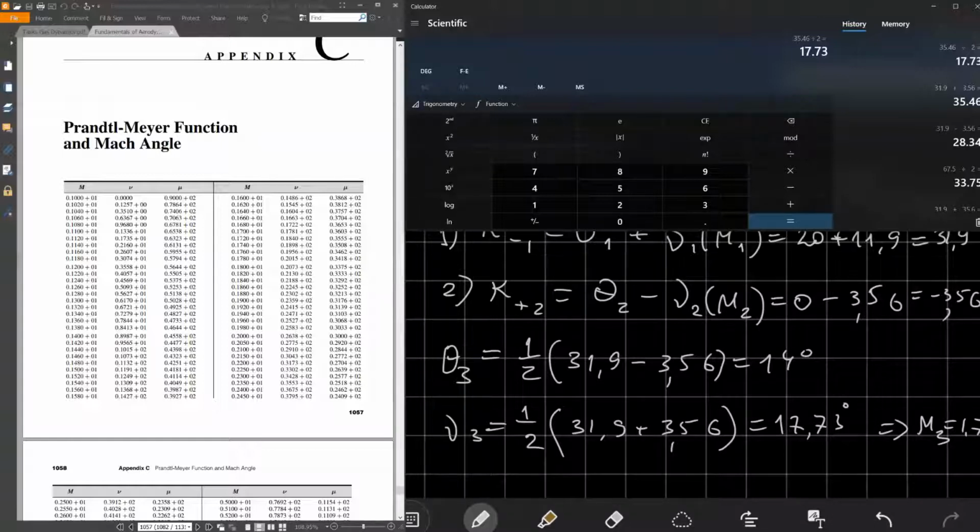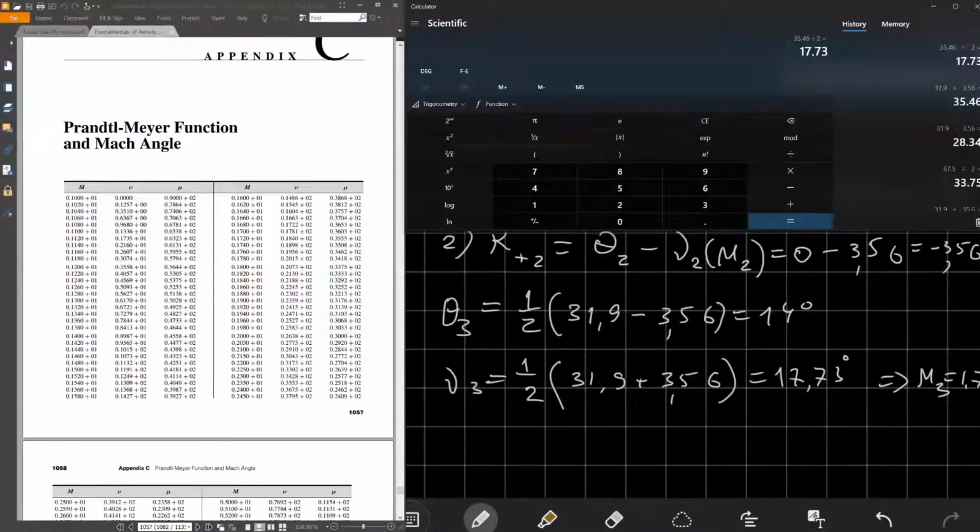Flow acceleration is happening in the middle between axis and the wall. So this is the end of calculation for the wall. If you would like to calculate thermodynamic properties, it's shown in the book how to make it. It's just apply isentropic relation